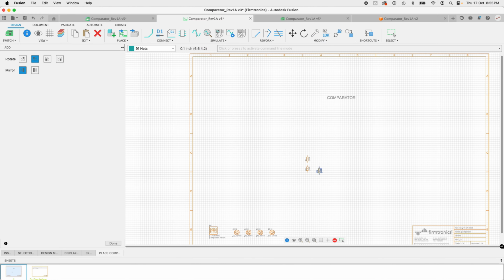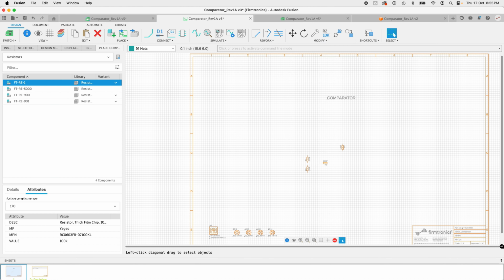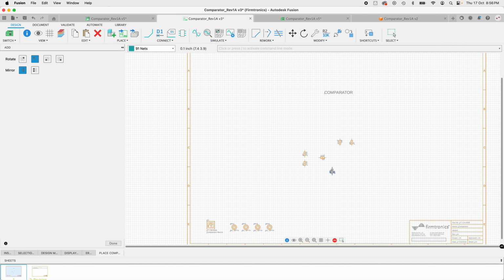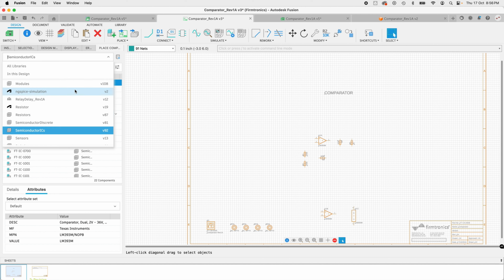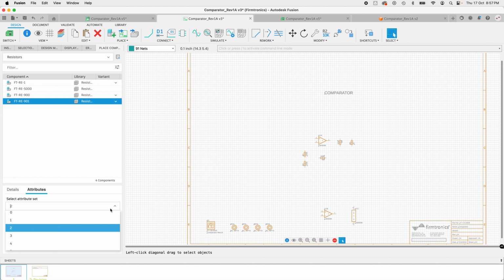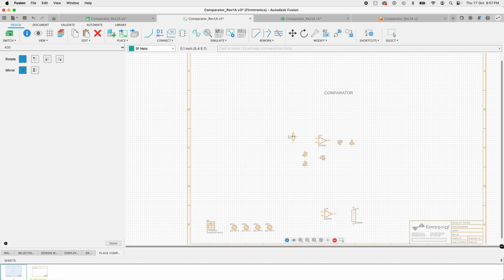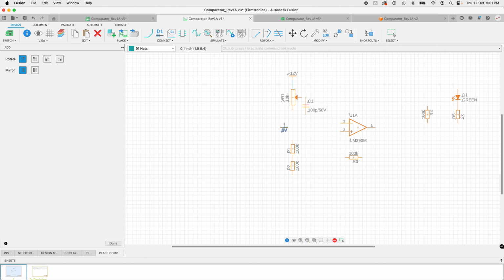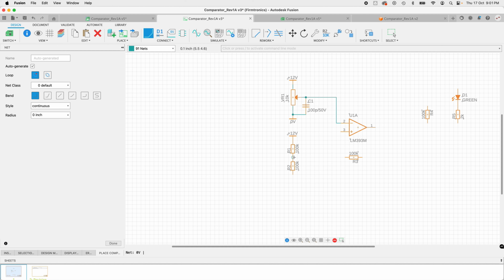Now we are going to design and manufacture a small PCB with the inverting hysteresis design that we previously discussed. The input will be designed to be driven by a trim pot. This will allow us to manually adjust the input from 0 volts to the input high threshold at 6.5 volt. When we cross the input high threshold, it will cause the output to transition to logic low.